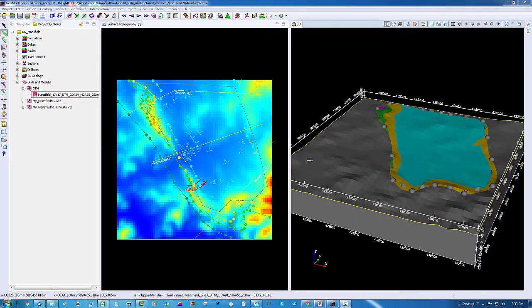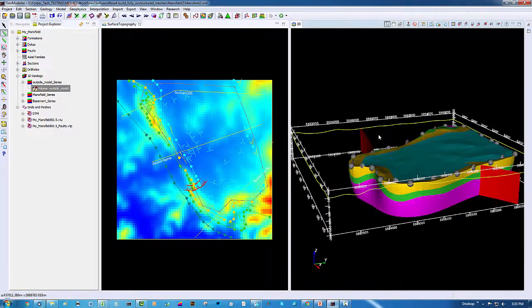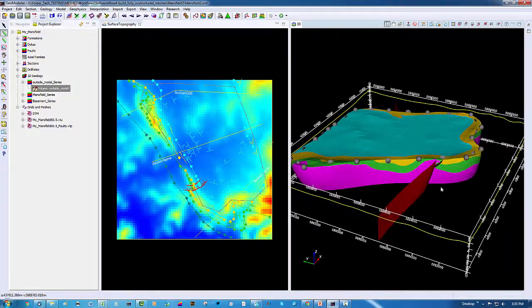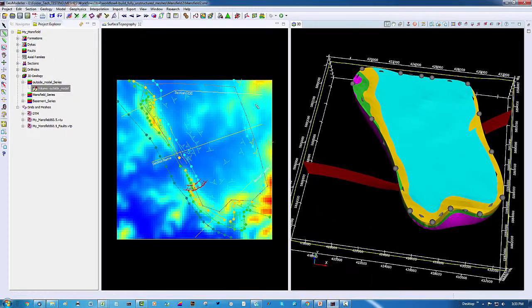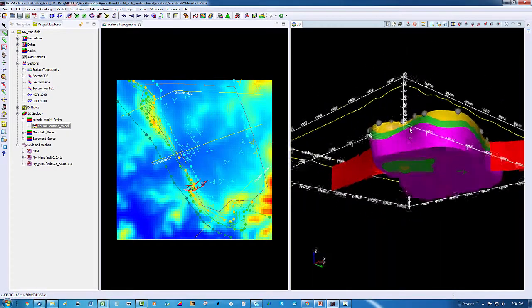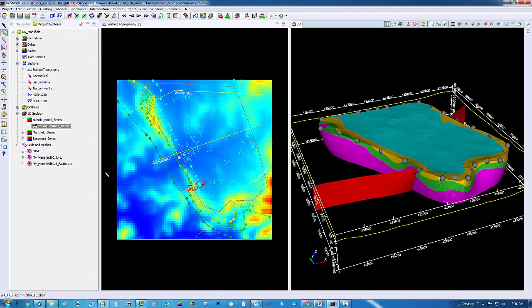When the model is complete, you'll see that you have the choice now to hide the outside model. This leaves precisely a limited model clipped to the topography as shown by the DTM. So it literally becomes a neat way in which to reject some volumes and not have them included in your meshes as you take them out into various numerical flow codes. So herein ends the demonstrations of today.